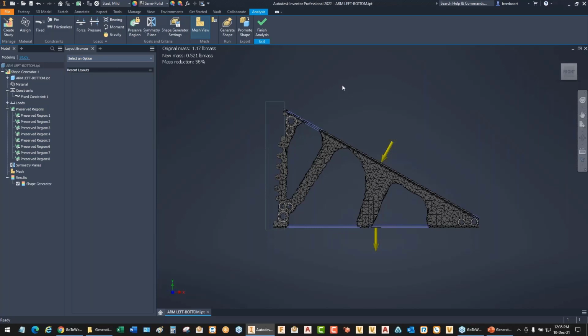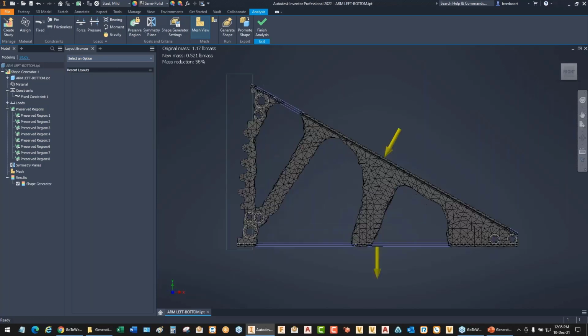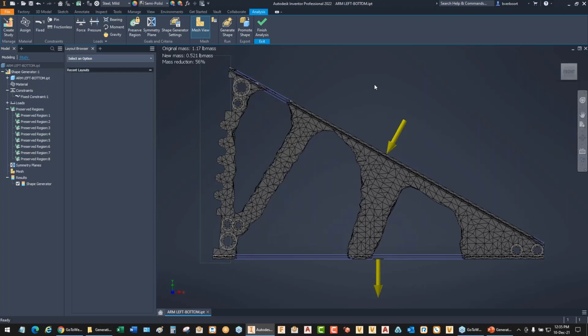Interesting what we get here. It has gone in and calculated where material can be removed from. It did that avoiding all of the areas that we set as our preserved geometry. So we see opportunity here for significant material removal, and it's not anything like the triangular shapes from the previous effort, and it's also more significant.